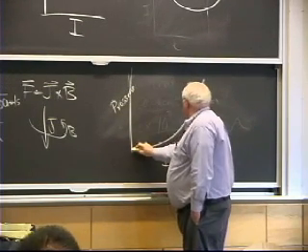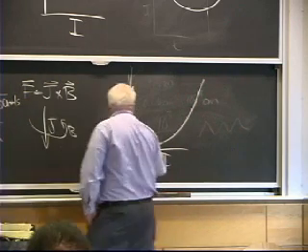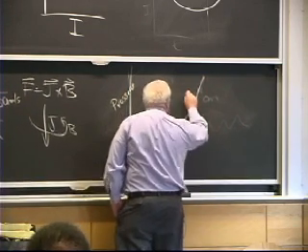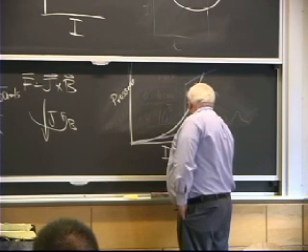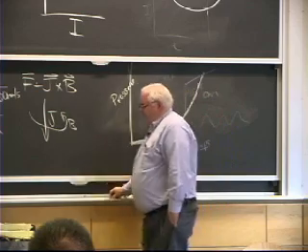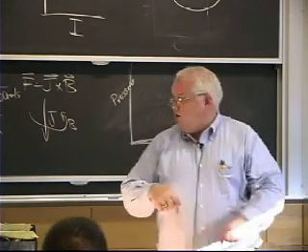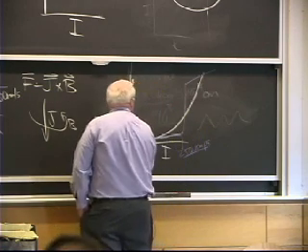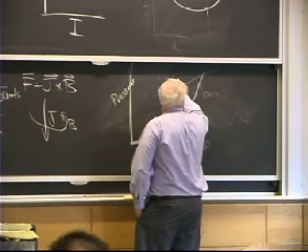If I were to plot the surface depression versus current, it kind of goes like this, such that at about 250 amperes, plus or minus 20 amps, I actually get enough surface depression that I start drilling a hole about 5 millimeters deep into the weld pool. So this would be about 1 millimeter, and this is about 5 millimeters.